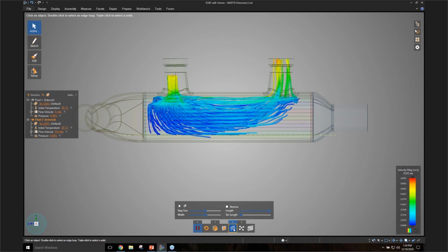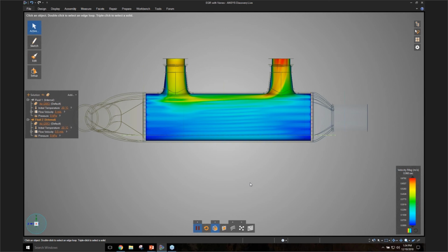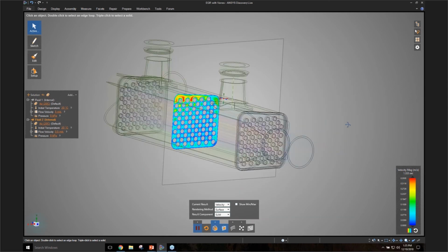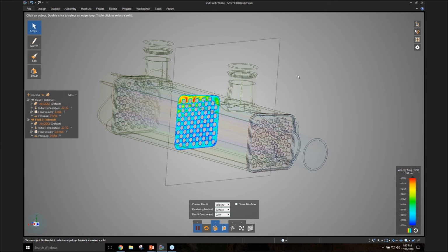And if I take a look at a cross-section view, like this, and if I look at it from this angle, you'll see most of the flow is kind of hanging around where you see the red areas, right? The middle section and the bottom right corner are not seeing sufficient flow, right? And this is not good. So I want to know, can I create some baffles to kind of force the flow to do something different, right? So once again, I'm going to use my built-in geometry tool, okay?